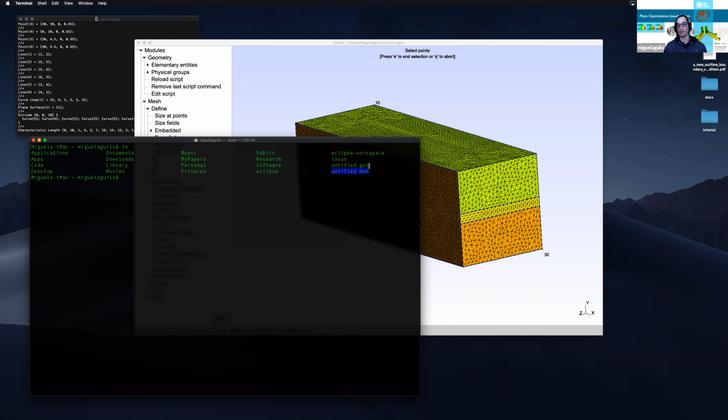The geo file, think of it as Gmsh is providing the CAD interface or support. So you can create your geometry and create your CAD geometry using the Gmsh tools. So Gmsh has this geometry kernel, which is the one that I used and showed you to build your geometry. Plato doesn't use the geo file. What Plato needs is the mesh file. So what Professor Hochhalter and myself need from you is the mesh file.